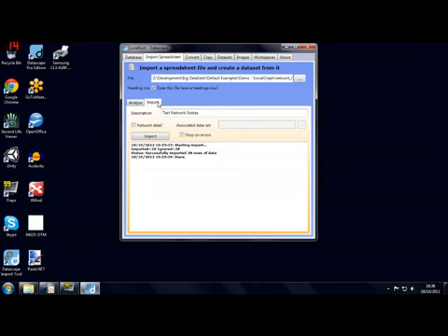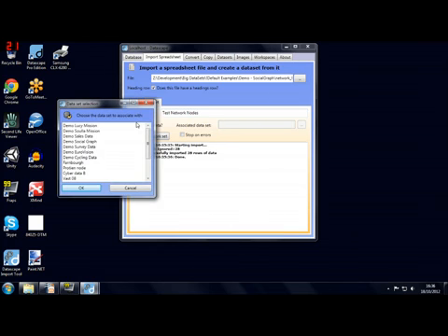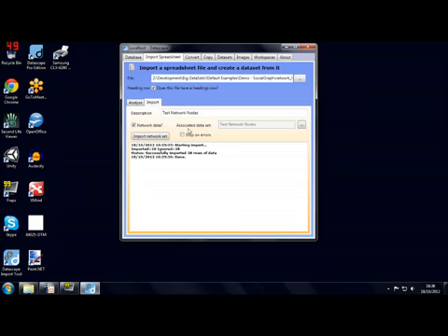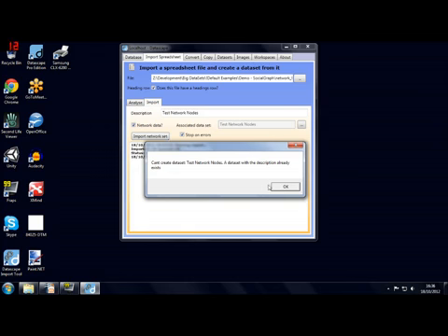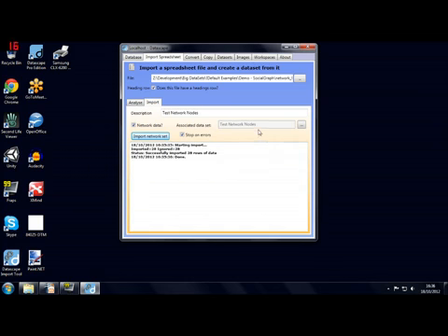Go back to the import tab. Okay, and this is the important bit. We need to click network data to show this is actually link data that we're bringing in, and then choose the associated node file and click on OK. And always a good idea to click on stop on errors just in case you get a problem, and import the data set. It tells me here actually I've forgotten to change the name, so call this links, and import. And here you see it's imported all 99 of those items.